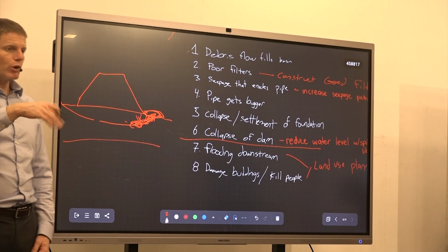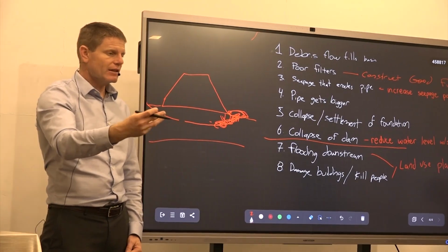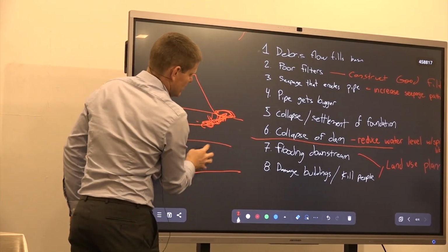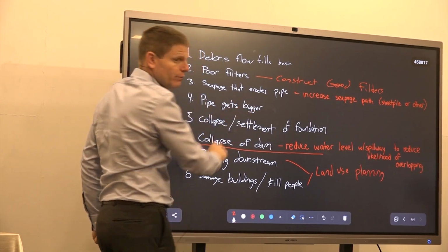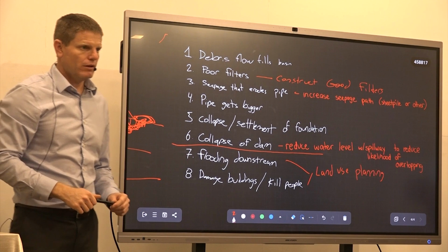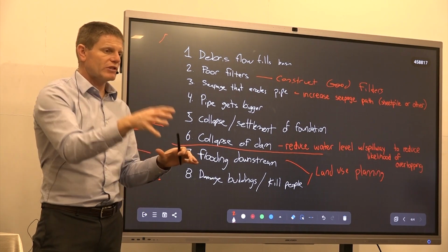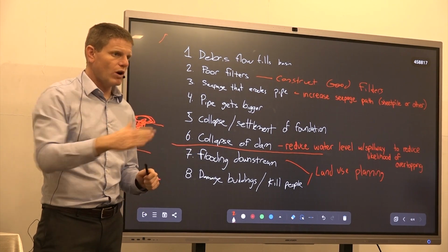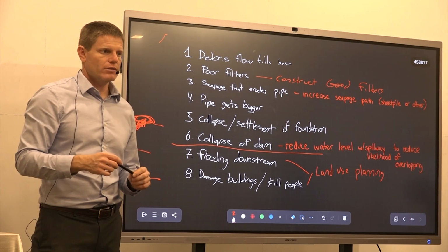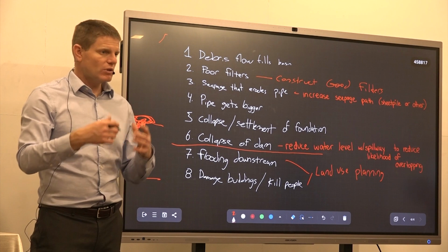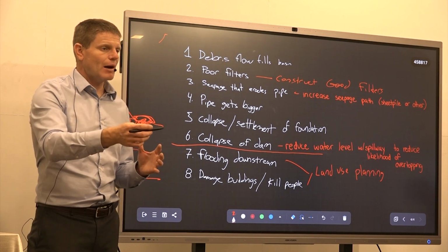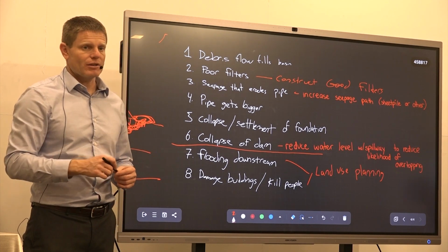And so you can have an emergency response that begins to actively prevent the pipe from getting bigger by placing coarse material over the downstream where the water is exiting the ground. So that's a possibility. It's sort of an emergency action that you would do as the last option that you have, but it is an option.